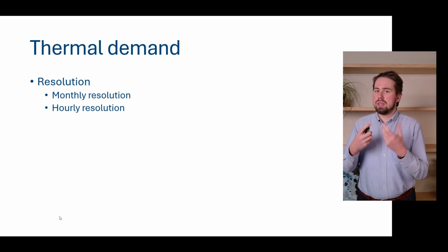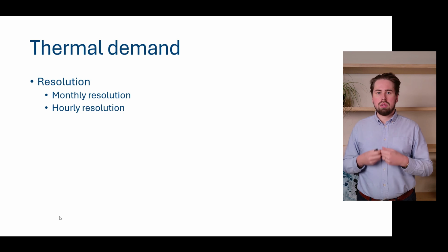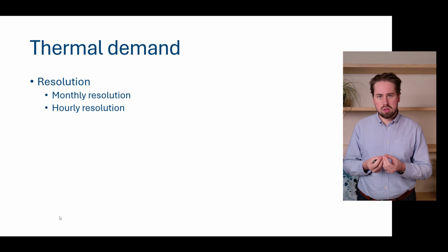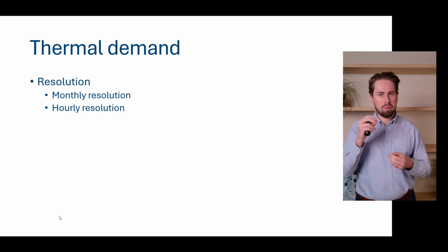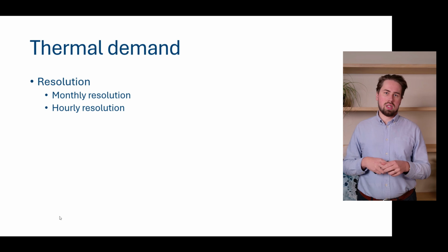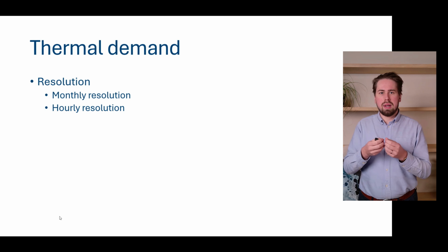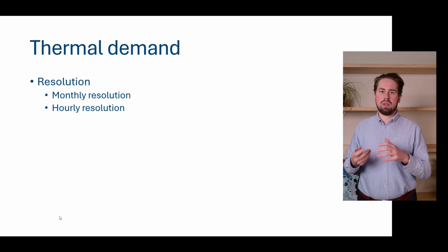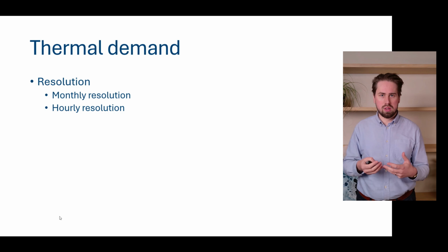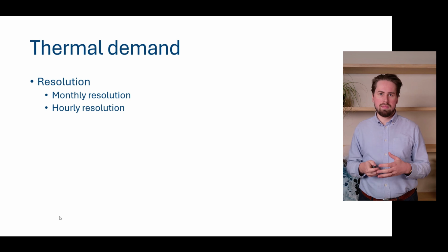If you have more detailed information available, you can also work with hourly values, where at every hour you know what your heating, cooling, and domestic hot water usage is. And this can give you way better accuracy, a way more detailed analysis of how your geothermal system behaves. We will come back to that later.